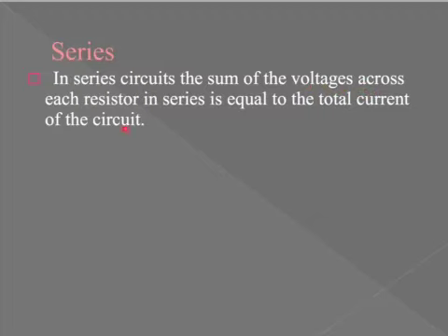We're going to come down here, and we know that we can use our V equals IR, except we want to use the I version, which is V over R. So we plug in: we've got our 9 volts divided by 17 ohms, so our current here is going to be equal to 0.53 amps. Now we're going to take this information and use it with these, still using V equals IR, but now we're going to find it for each one, and they should total up to 9.